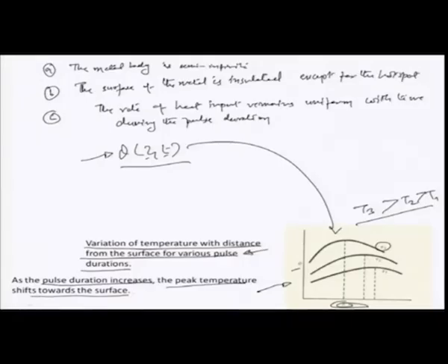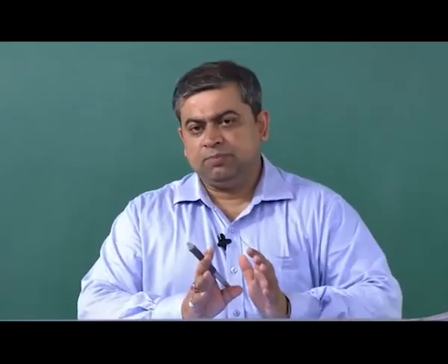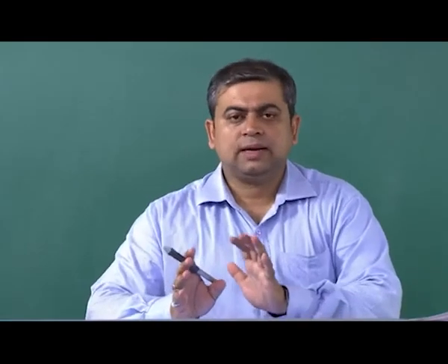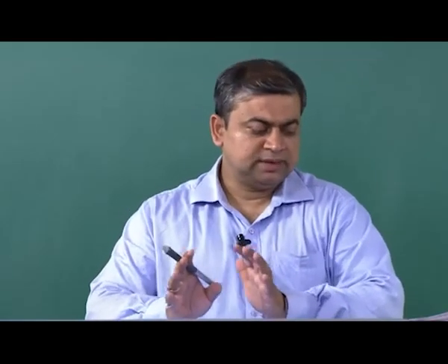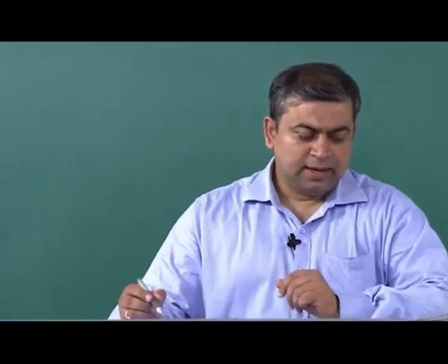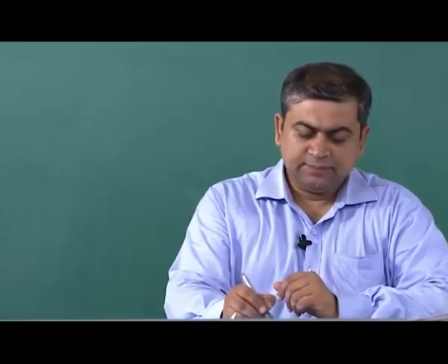So, we would now like to perform a sort of dimensional analysis for also checking the consistency of the various parameters of cutting with respect to the EBM process with respect to the material removal rate, using the Buckingham's pi theorem. So, the first thing of importance is to be able to look at what are the independent and dependent parameters in the whole EBM machining process.